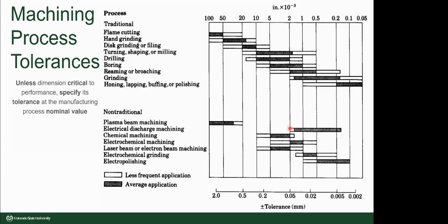The tolerance that a particular machine right in front of you can achieve will depend not only on what type of machine it is, a lathe, a mill, a grinder, but also the brand of the machine, the model, the maintenance and upkeep that's been done on the machine, and the machinist's skill. All of these can affect what tolerances you can hold with the machine. So you, as the designer and engineer, should always be aware of the machining process used to make a part feature.